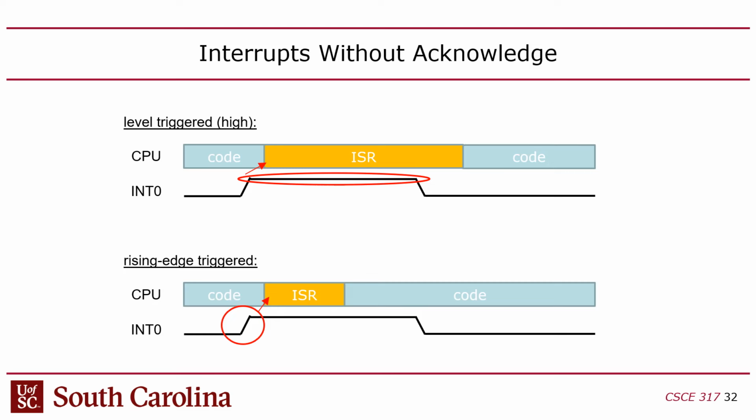what the problem is. Sometimes there's another register called the cause register. The MIPS architecture had a cause register. You probably didn't cover that in 212, that's kind of esoteric, but in the MIPS, the first thing you checked was the cause, which was a code for which peripheral actually requested the interrupt. Once you know that, you have to branch off to another interrupt service routine for that specific peripheral, and then do programmed I/O on it to figure out what it needs, and then do whatever. So it really depends on what the hardware is.